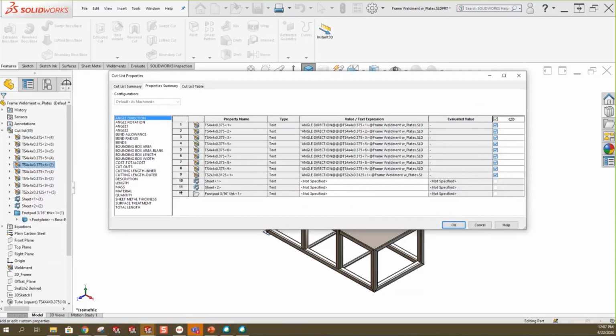Is this how you would build a trailer? I would say yes as well. So Jeremy's saying, yep, building a trailer. Again, keep in mind though, the more complex it is, the more of a resource hog it's going to be. So does it make sense to build, say, the frame with the panels as a part, and then at the assembly level, here's where I'm inserting the kitchen table and where the stove goes, where the shelving goes? I could certainly do that, especially if you have components that you're using over and over.